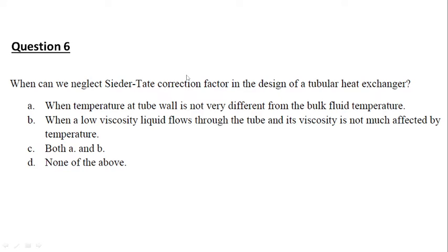Also, when a high viscosity liquid flows through the tube and the viscosity is affected by the temperature, then we need to consider the Sieder-Tate factor.